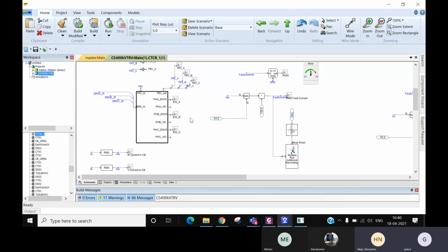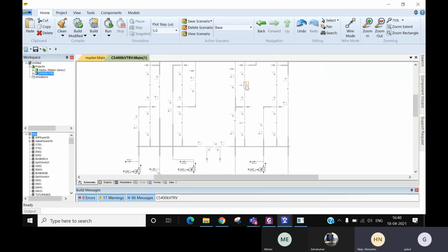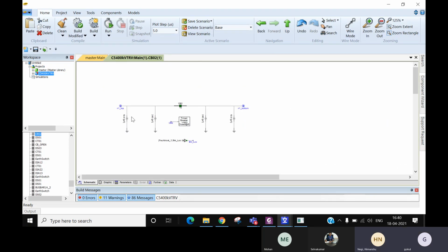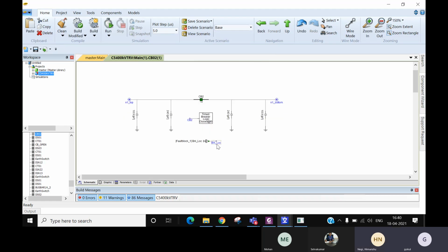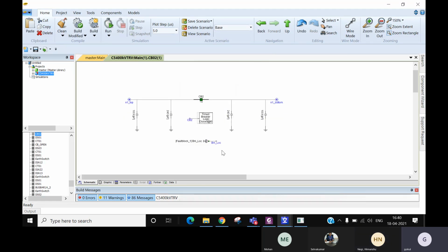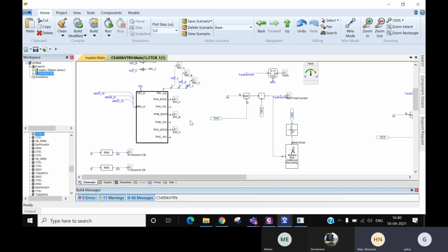And what do you do with the other breaker on this same bay but towards this 220 kV side? Here I have measured the voltage. Here also I'm just opening it, like you can see, right? Same time I'm opening it, but I have measured the fault current here and here. Only on this breaker the fault current is higher. So I took this worst case and I have done it. And that's why I have included the TRV.